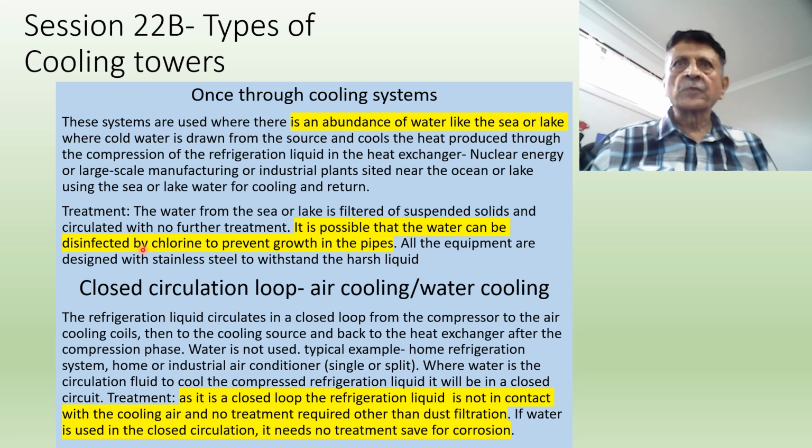However, in order to prevent mollusks and other things that can stick onto the sides of the pipes, they will add some chlorine or other forms of anti-deposits. All the equipment designed for the use will have to be made of stainless steel to withstand the harsh water or high sodium chloride solution.